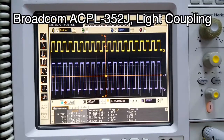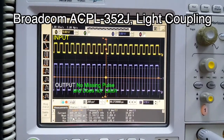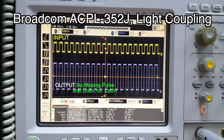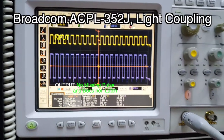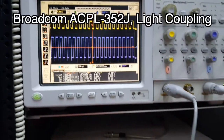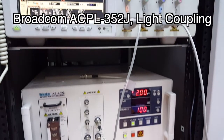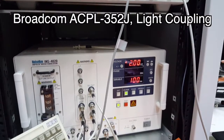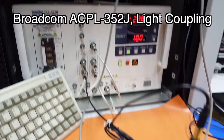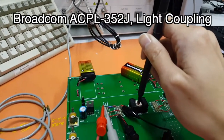The last driver we're going to test is Broadcom's ACPL-352J. This is a gate drive optocoupler, which uses light to couple the signal across the reinforced isolation barrier. The ACPL-352J is a 16-pin driver with integrated overcurrent protection. The Broadcom gate driver is good and does not latch or have any missing output pulses at the impulse noise generator's highest rating of 2000 volts.